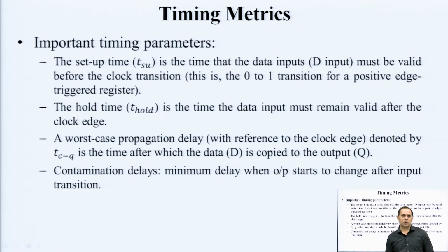Now, since we are talking about clock and memory and triggering and pulses, there are a lot of timing issues associated with sequential circuits. A well designed sequential circuit will always take into account all the timing overheads. Suppose you have applied one particular input and you have to wait for some kind of trigger, which is generally given by the clock. Until that trigger comes, some time elapses, and the input should remain available for a small amount of time before you can actually do some processing with it.